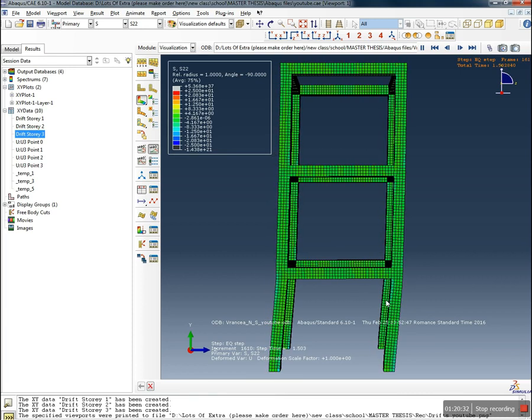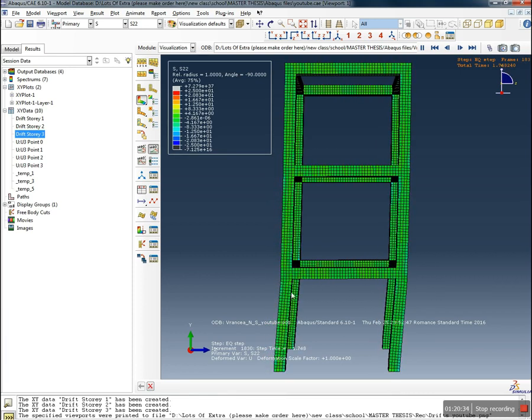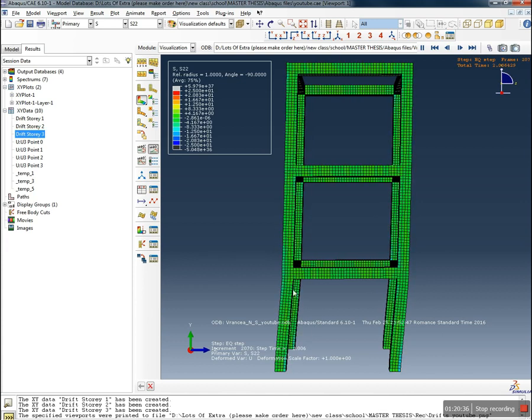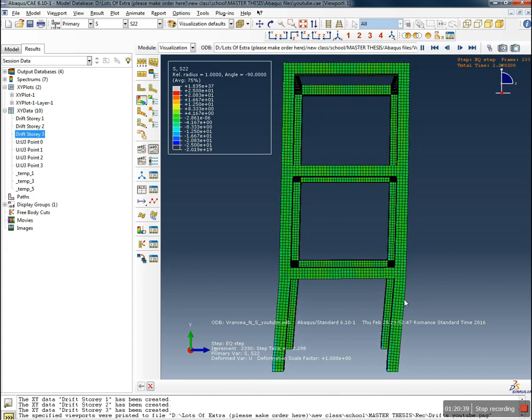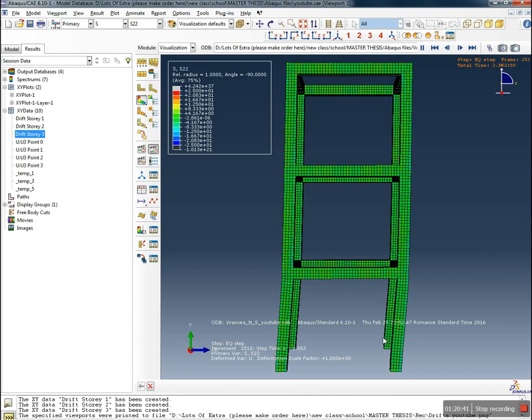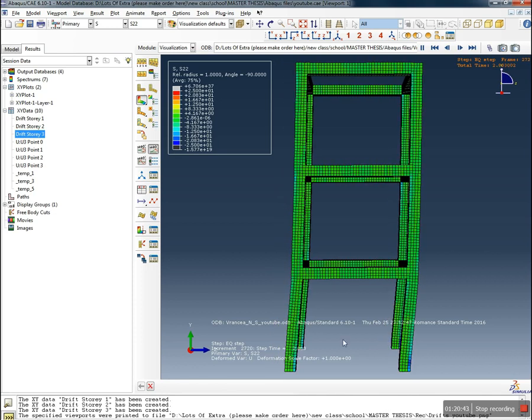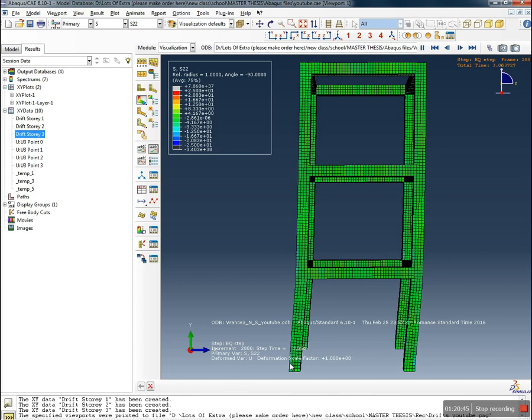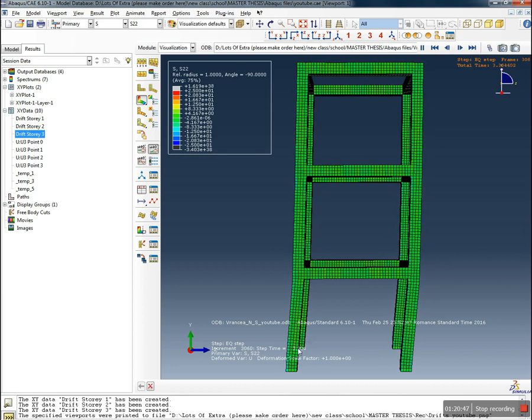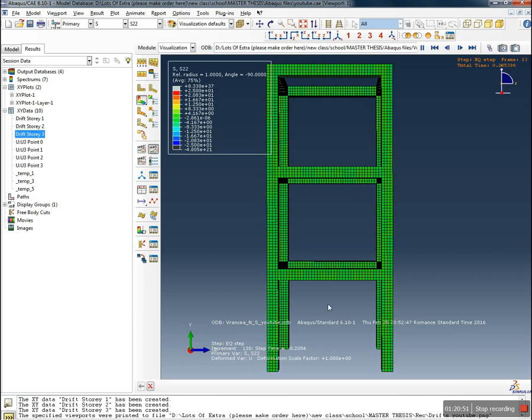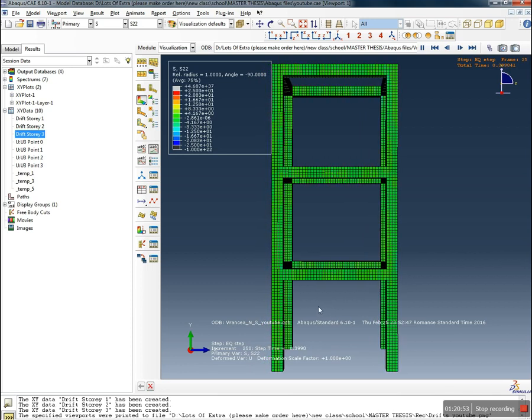Yes, and that's what I mentioned the solutions for: increasing the height of the story for extra flexibility, and also placing the stirrups much closer to each other. Of course, this model has no stirrups, but it's not that difficult to define and model them.